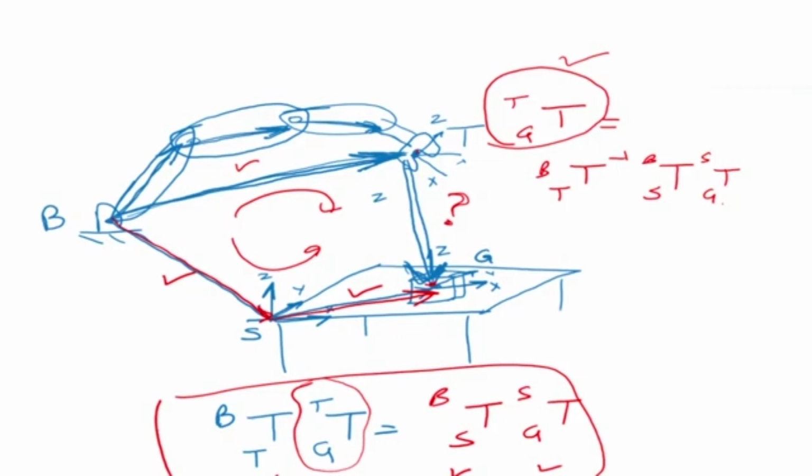So this is the use of the homogeneous transformation matrix in robotics: we essentially have to go and catch something at a particular distance or wherever it is placed, and the controller has to find the distance from the end effector to that object using this matrix multiplication, the homogeneous transformation matrix. Then it can go and catch it. So this is the use of the homogeneous transformation matrix.